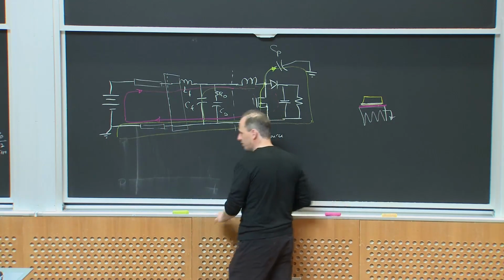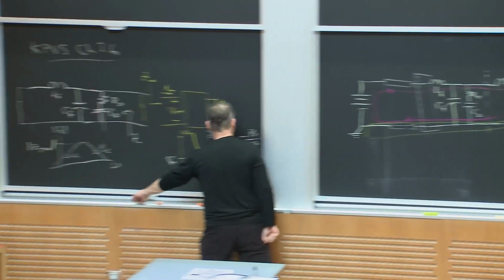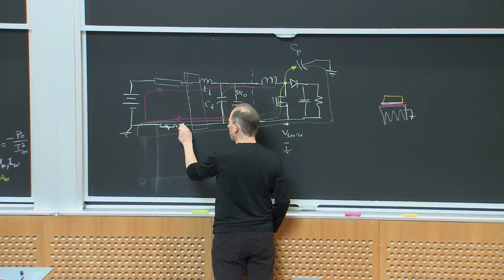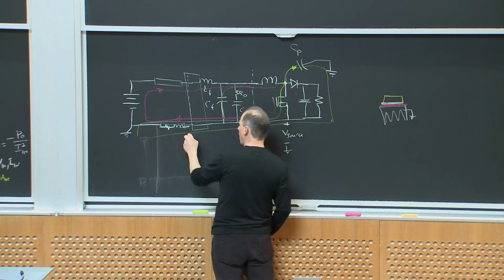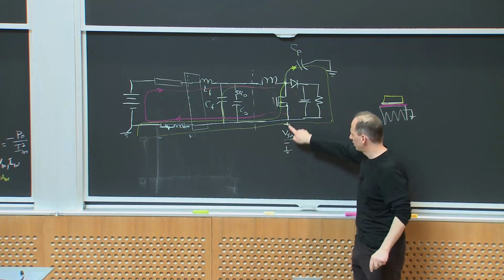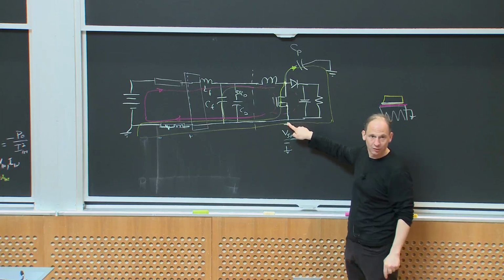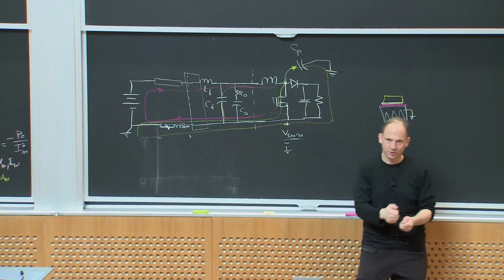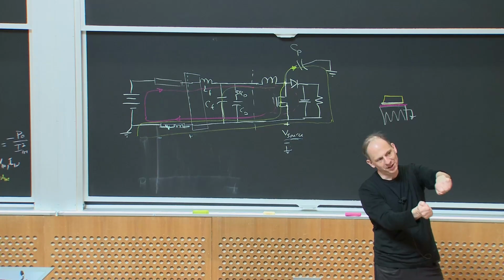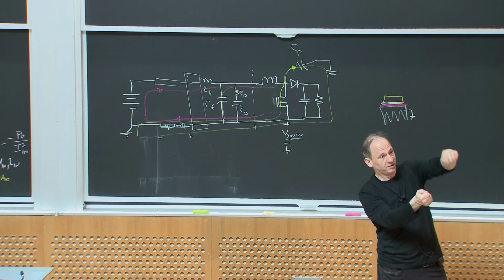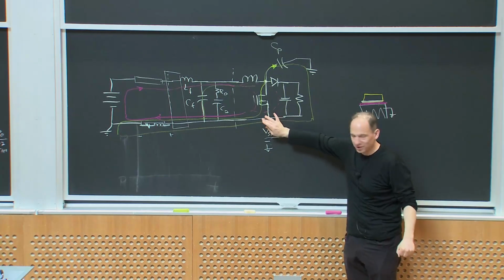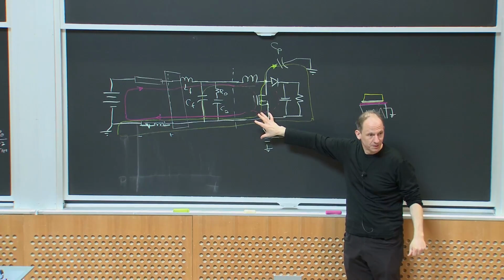If this pathway has some parasitic resistance and maybe a little parasitic inductance from all the wiring, I can develop a voltage drop across here. And so this voltage is non-zero. I'll see what's called ground bounce. And maybe you've experienced this when you've tried to measure just ground on some circuit you're building and it looks like it's got a bunch of high frequency junk on it. That's exactly due to this kind of phenomenon. Okay?